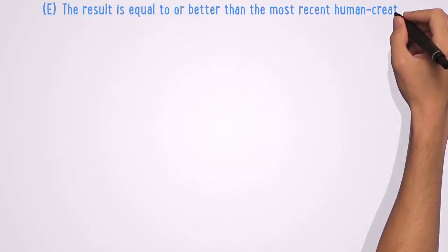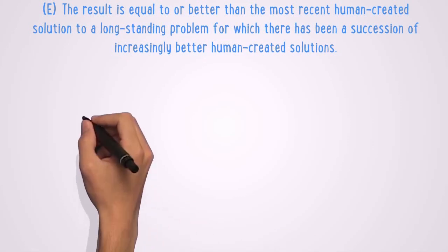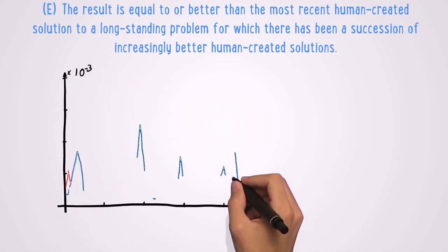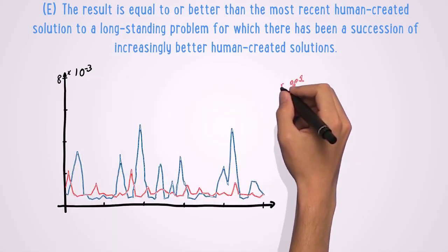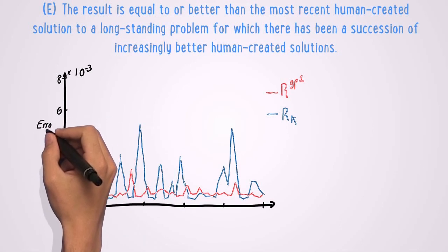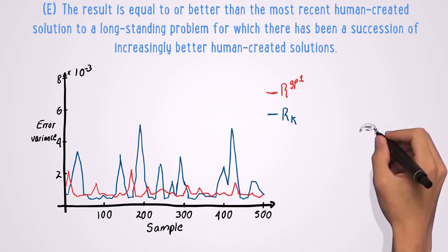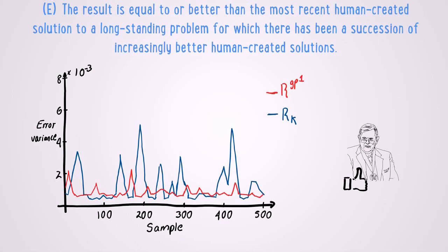For criterion E, the Evolved Extended Kalman Filter has outperformed the original Extended Kalman Filter. This can be explained by the Kalman theory assumption that the noise affecting the measurements is zero mean Gaussian, when in practice and even in simulation this is not perfectly guaranteed. In contrast with the traditional Extended Kalman Filter, the GP builds suitable solutions using the non-perfect noise and considering only intrinsic variables from the filter and the system's noisy measurements. Thus, its implementation is straightforward and does not require further adjustments.